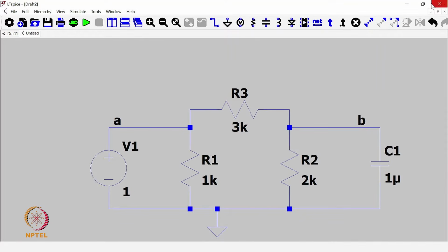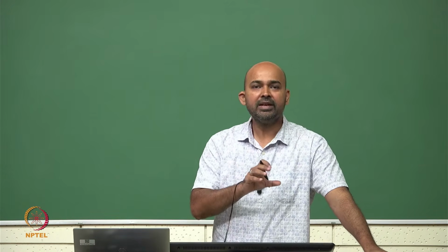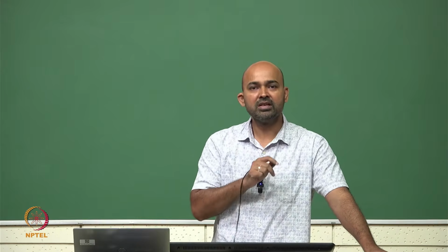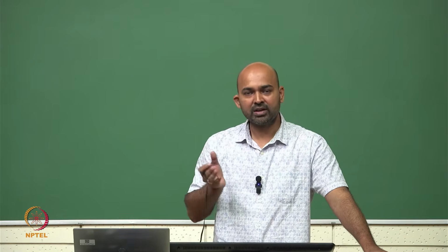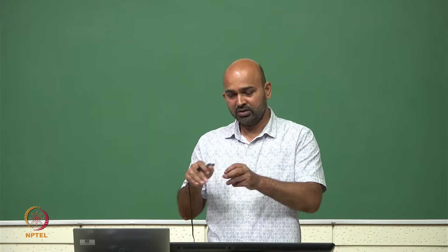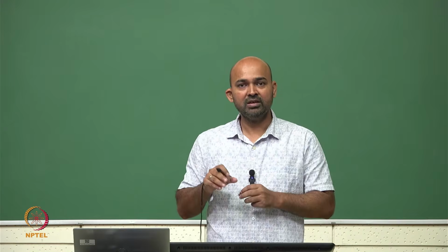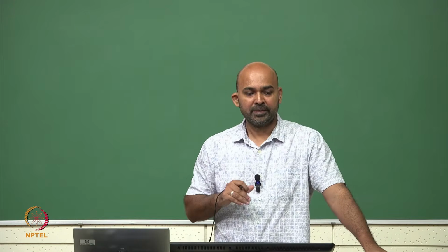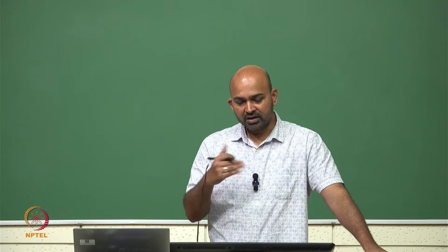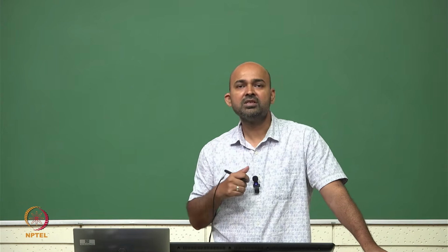So, these are some standard syntax of SPICE which you need to know. Coming back to the discussion, we just saw how we make a pictorial representation of a circuit in SPICE and LTspice and convert it into the textual form, which is the netlist. This netlist is going to be simulated using SPICE software. SPICE is going to solve all the matrices needed to arrive at the nodal voltages and branch currents.